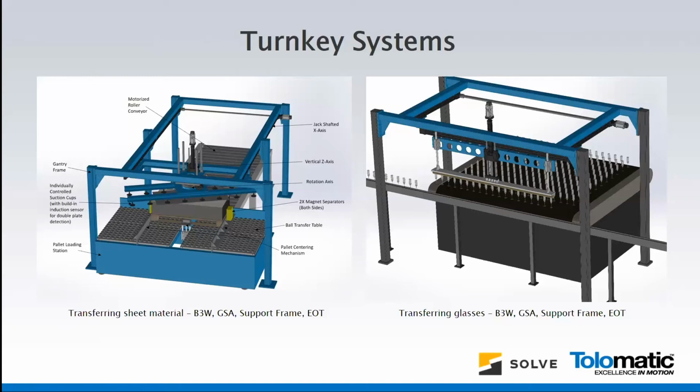And on the right side, somewhat similar actuation of conveyor transfer of product, but slightly more sensitive in the sense that we were moving glasses and not sheets of metal, so glass material. But the concept is the same. You have a heavy-duty steel frame with two jack-shafted actuators, and then a Y actuator across, a GSA moving the load up and down, and then some sort of pneumatic vacuuming system to grab onto those glasses and move them from a conveyor to another conveyor that runs 90 degrees from the first one. So just some examples of turnkey systems, and there's a couple more on the next slide.